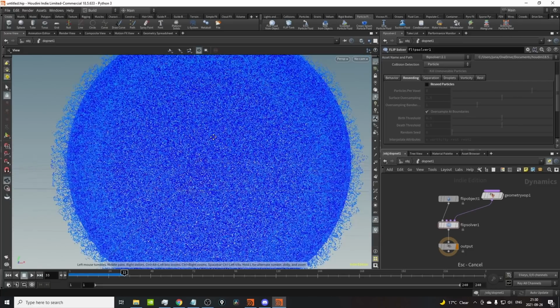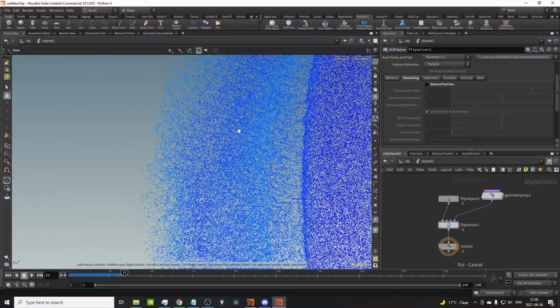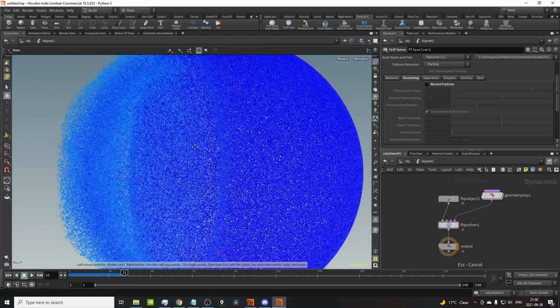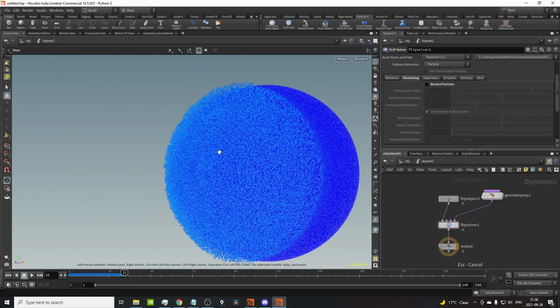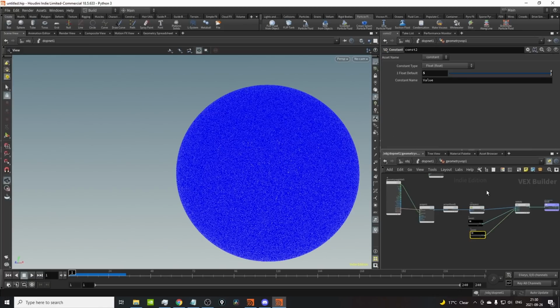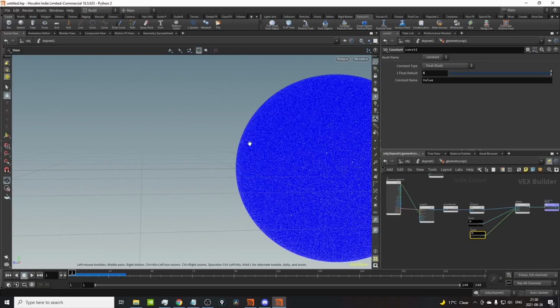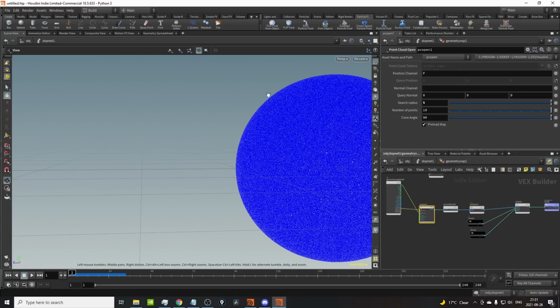So all of these guys, they're just pushing away from each other, and they're just trying to spread out as much as possible. Now, the thing is, we're looking up in a perfect circle, right? Which means we're not masking this out based on where the particles are to begin with. We're just saying everything around the sphere in a 5 meter radius should be pushed away, which means out here we also have divergence. And that might be that you want that, but in our case, let's refine this a little bit and just make sure that it all stays within a decent distance to the shell.